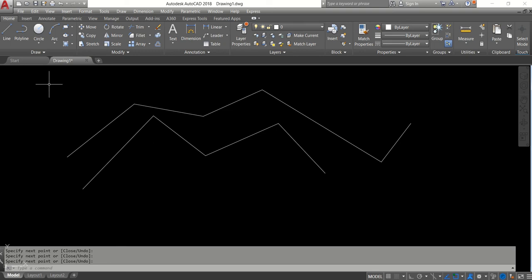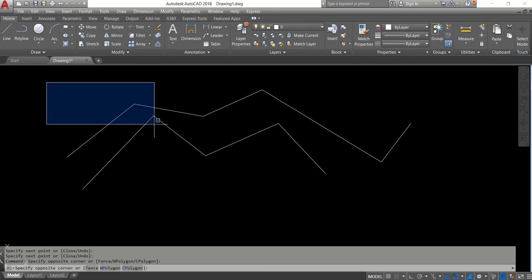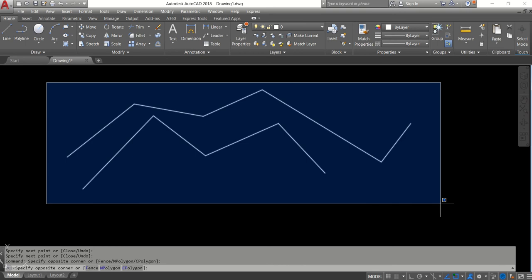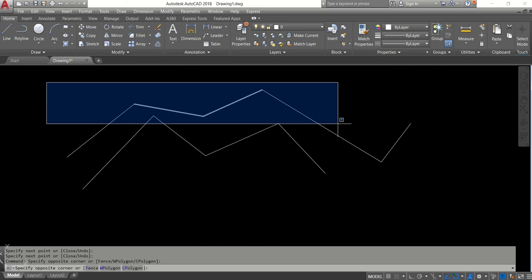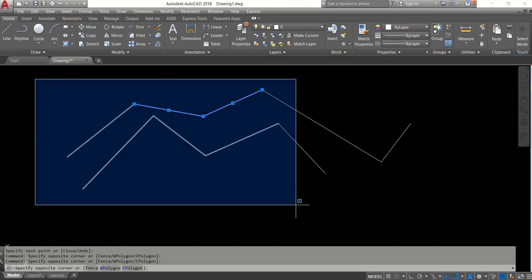Now if I see the selection tool in AutoCAD, there are different ways by which I can erase this line, right? The first way is I can simply, without giving any command, click on the top left, and I will make sure that all of the elements are included in this window, right? You can see the border of the window is a continuous line, and within the window is a blue transparent shade. So when I select all these lines, and all the points of the lines are within the rectangle, they are getting selected, right? The moment I reduce the size of my window, it will select only two objects, right? So it has shown me these two objects are selected, because all the endpoints are not included inside the window.